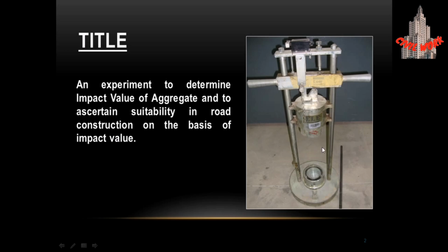The diameter of the hammer is 100 millimeter, and the height from which the hammer has to fall on the aggregate is 38 centimeter, that is, it has to fall freely from a height of 38 centimeter.